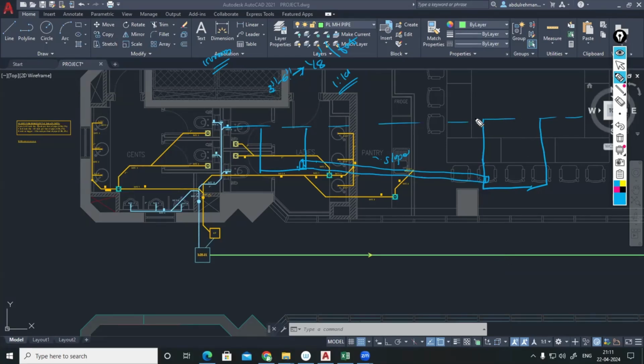Okay. So this is the cover level. And what about the invert level? Normally for invert level, in most cases, people will be considering the invert level of the inlet pipe for all the other manholes. Accordingly, they will be calculating the length also. Because this is the cover level and this is the invert level. Cover level minus invert level. Cover level is 0, 0. Cover level minus invert level, they can calculate the depth. That is one method, the first method I am following now. Cover level minus invert level, you can find the depth.